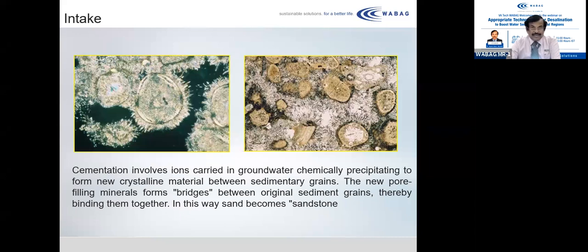So this is the main disadvantage in any lateral type arrangement or neo-drain arrangement, or in the Ranney well or single bore type wells. So we need to be very careful in analyzing the possibility. In a bore well test, you have to do a drawdown test in order to ensure that you get enough water for at least 10 to 15 years for the operation of the respective plant, and they are suitable for medium or low capacity plants only.